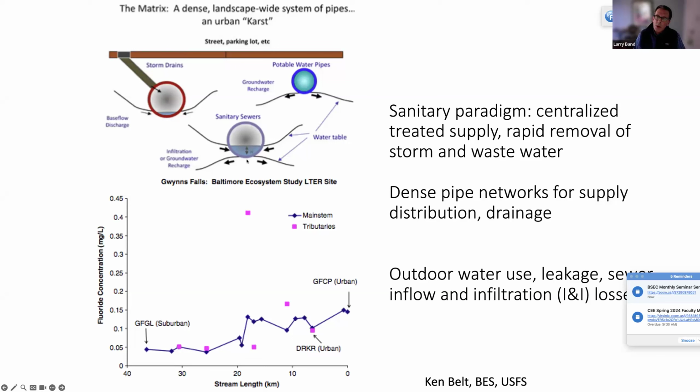And the sanitary sewers, although they're designed to be separate from the natural environment, as Claire and Aditi have shown, could actually absorb a substantial amount of groundwater inflow and surface inflow and infiltration. Some of the numbers are actually quite surprising, but seem to be fairly common. Up to 30% of the rainfall may be disappearing down these pipes. Lower than that in most areas, but that's something we need to be able to handle.